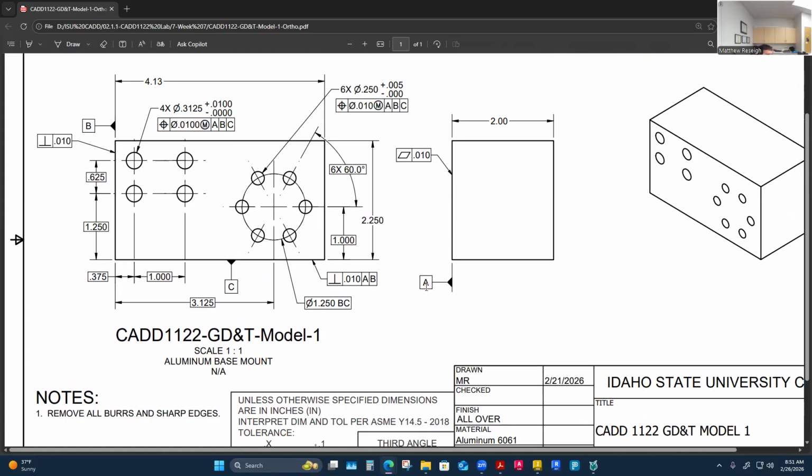Okay, let's just establish datum A along with this control. Datum B is left side surface, and it's being controlled 10 thousandths perpendicular. It doesn't say to which datum, so I feel like this could be an error. Likely this should say perpendicular to datum A. That would be true. It's perpendicular to datum A. So I bet Inventor will want us to add that. Let's see what it does with my annotations.